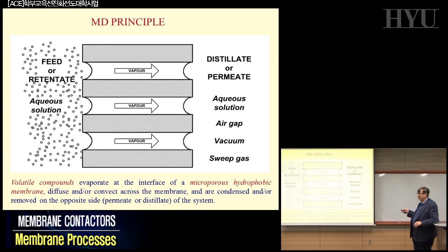We can also realize this by a different concentration. Instead of calling it membrane distillation, you call it osmotic distillation, or what people are working on in forward osmosis. You can put a draw solution, a very highly concentrated solution, on this side, and you can extract by the difference in the activity of the ions across. But normally you put a delta T.